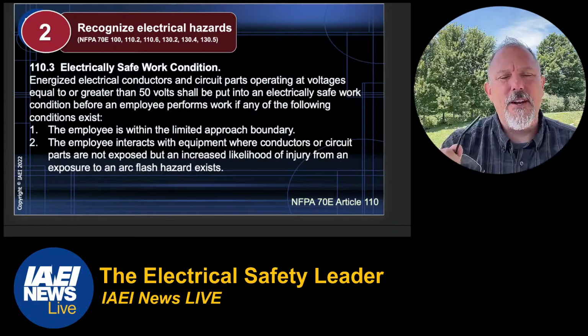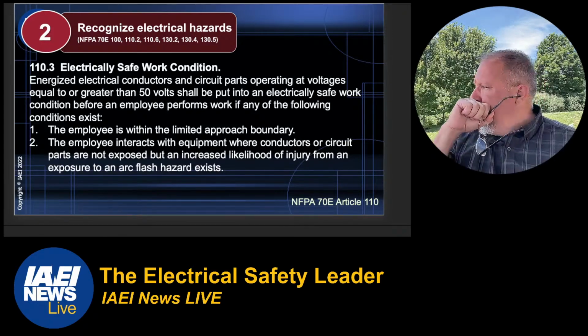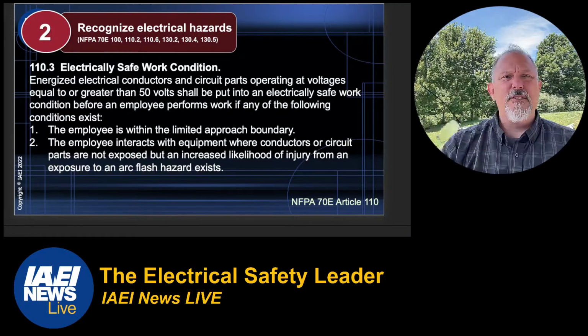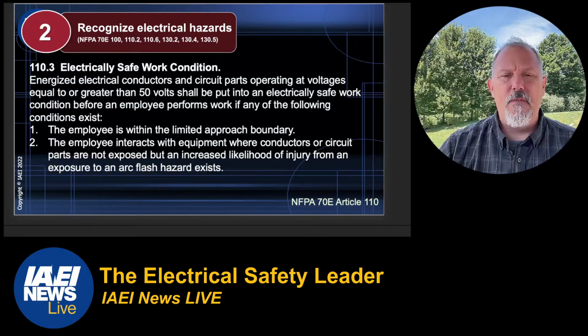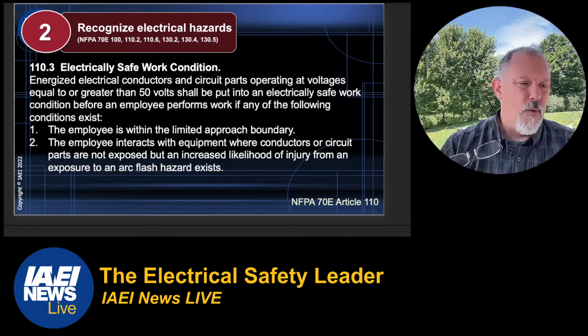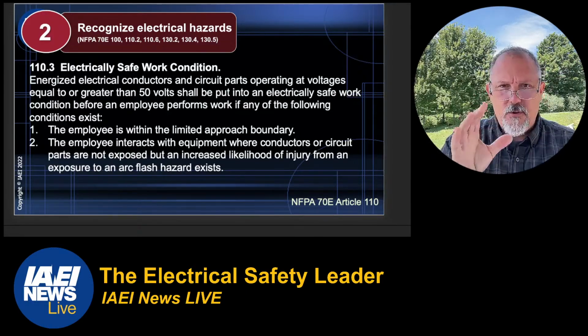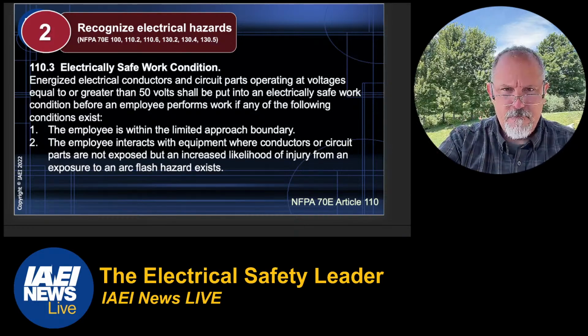But then you also have to identify and understand the equipment that you're looking at. You might look at a piece of equipment and think, hey, there's nothing in here that could possibly be more than 50 volts. But if you don't understand that equipment, then you really can't tell whether or not you have a hazard there.